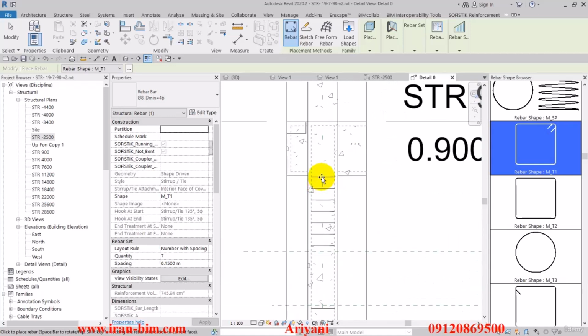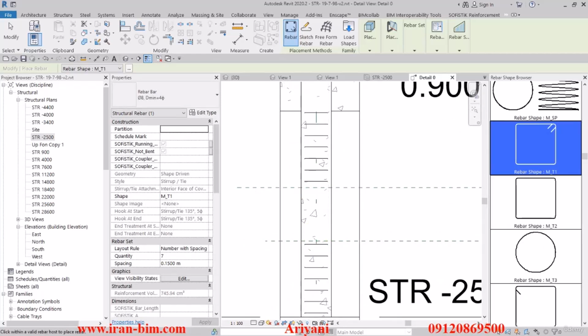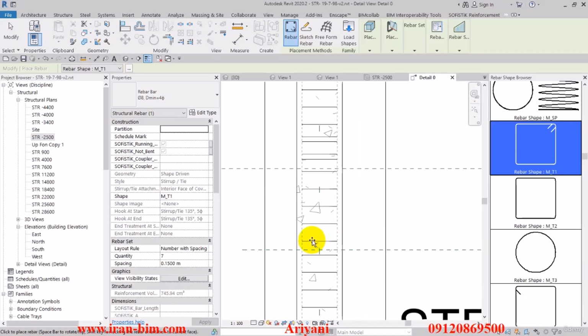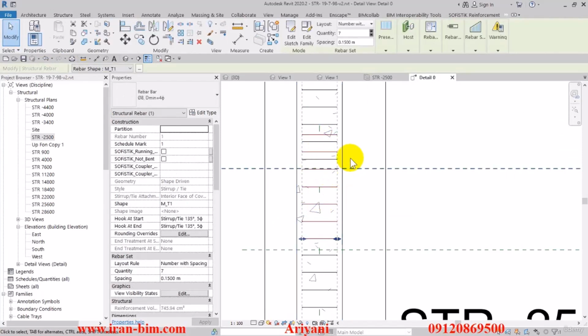After that, we have the middle part. The middle section goes from minus 2.5 up to the height of plus 90, and here it says the same thing in the plan, 7 type 10 rebars with a spacing of 50. But we can't really fit 7 rebars here. This is an AutoCAD file issue. Here you have to fix the issue yourselves. So then we'll select this, and then let's see what number we should choose.